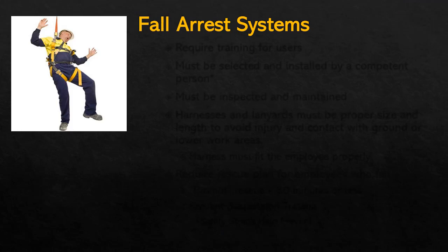There are sometimes situations where a person needs to work at heights and they're exposed to a fall hazard, but they also need a lot of freedom of movement in order to be able to do the operational things up there that they need to do. In that case, personal fall arrest systems will be necessary. Now, personal fall arrest systems are complicated and they require extensive training for users. You can't just give somebody the equipment and say, go work on the roof. People that are going to use personal fall arrest systems need extensive training.